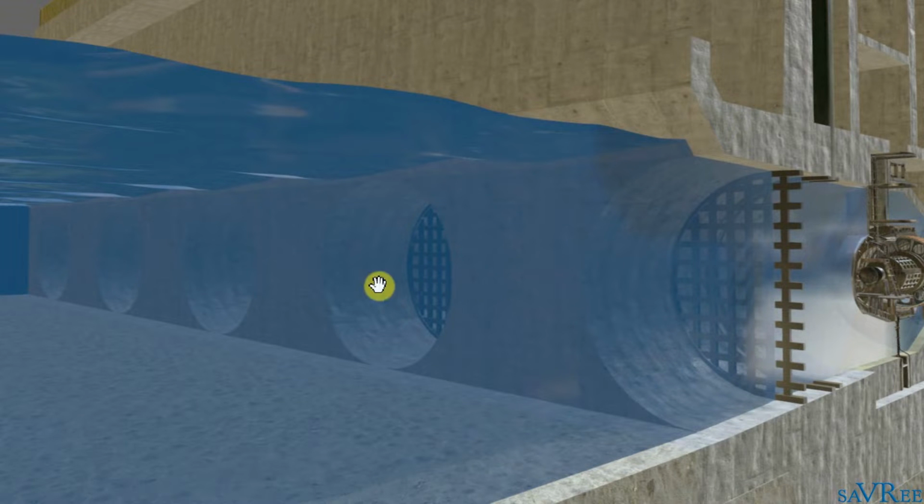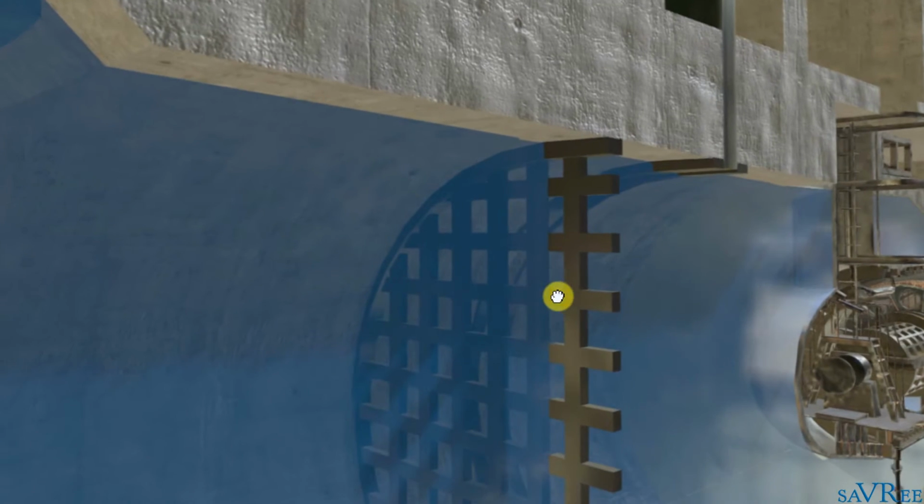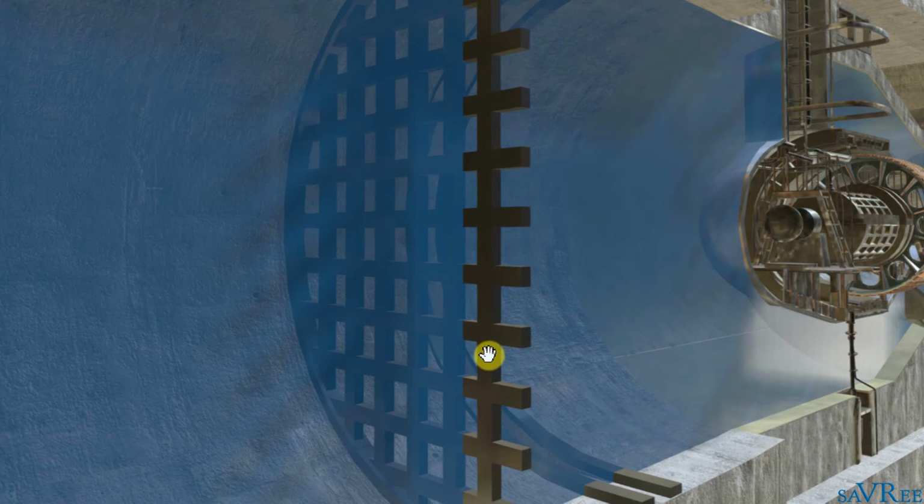You can see we've got a load of inlets and discharges on this side. We've got a trash rack, which we'll use for picking up bits of rubbish and trees, etc. Anything that might want to go through here and into the penstock and damage our turbine runner.